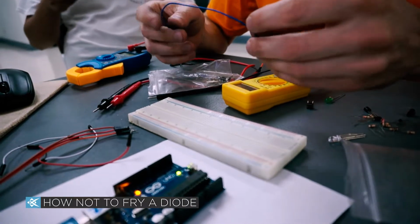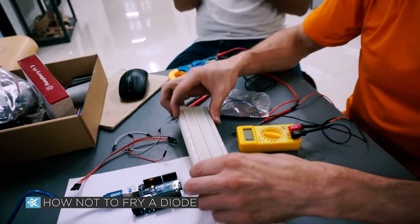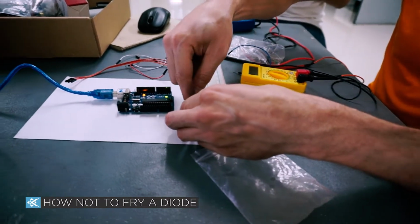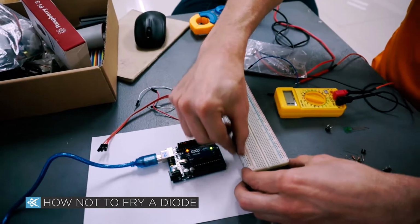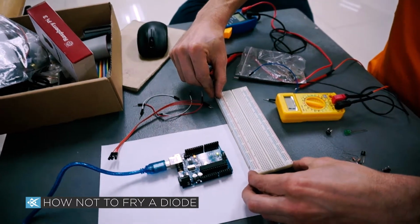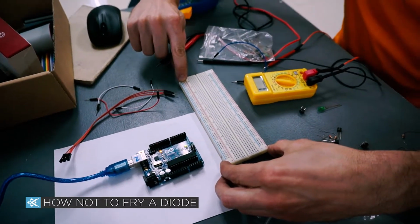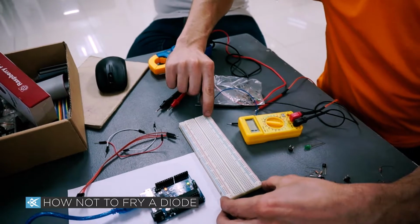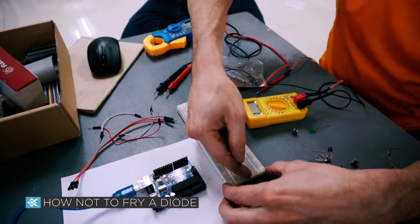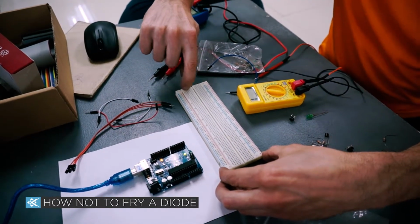Usually a good way to do things is with what we call a breadboard in electronics. The way they work is that the top two lines and the bottom two lines are all connected together. So all of the top line is connected, and all of the second line on top is connected to each other, but the top and the bottom ones are not connected to each other. They're independent. Same here, so they're connected that way. And here in the middle, that line cuts everything. Otherwise, all the vertical ones are connected to each other.